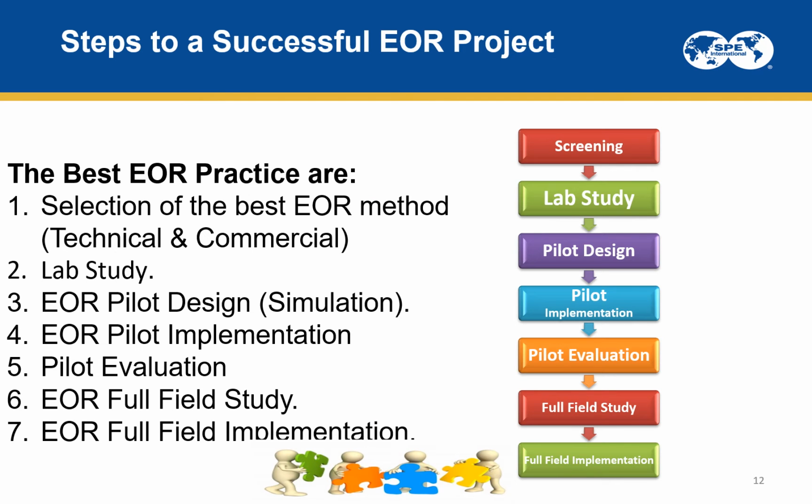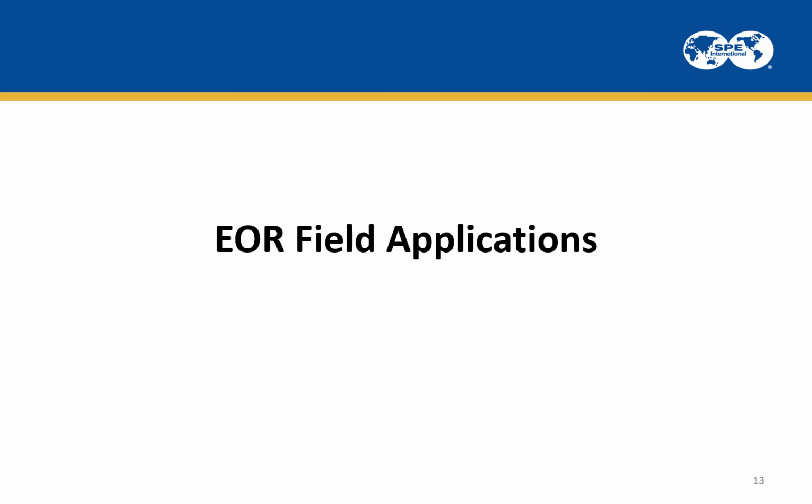As a general phase, the first step is to conduct technical and commercial screening to select the best EOR method for this field, and then conduct laboratory studies, and then pilot design, including simulation and so on, and then go to implementation. After implementation, we have to do pilot evaluation. If it is successful or not, then we can go for full field study and full field implementation. These steps are very important for the success of EOR projects.